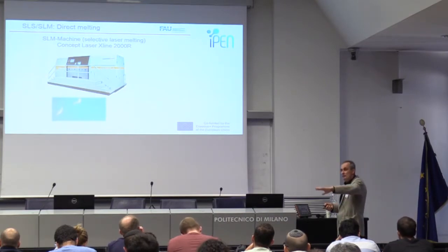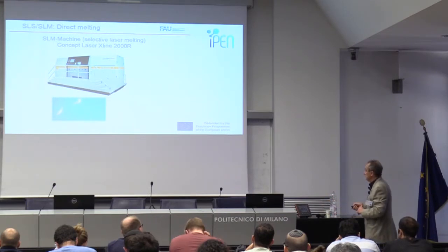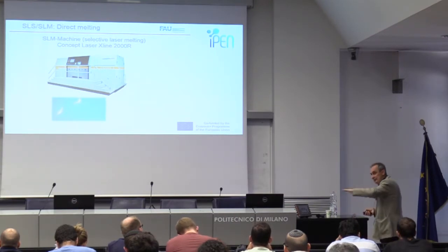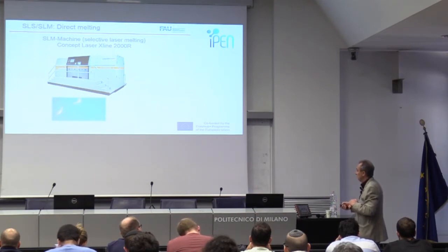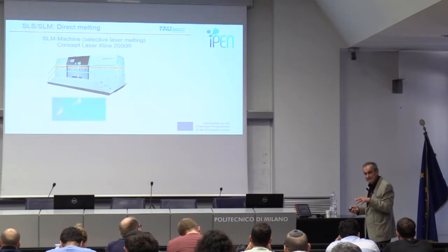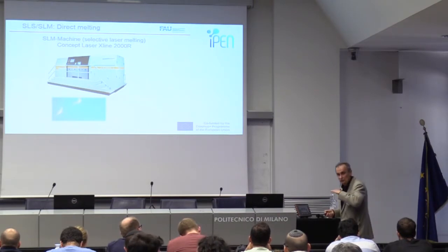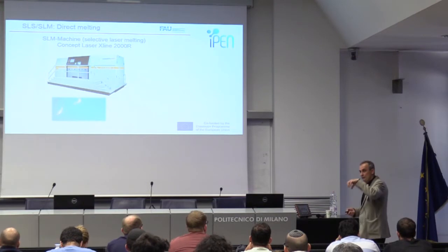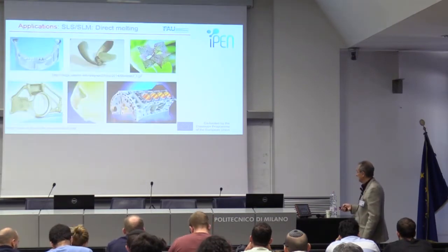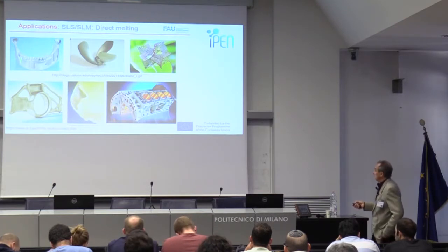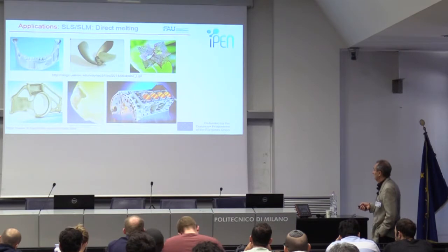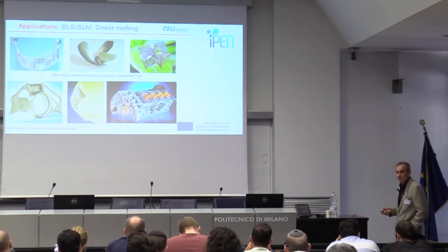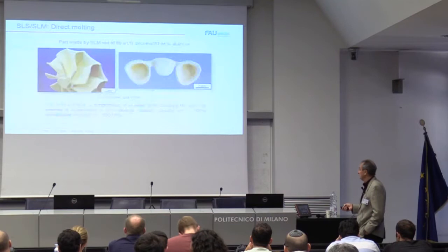You make a sheet of the materials which you would like to synthesize. You sinter with a laser only a small sheet, your slice. After that, you make this casting again, next sheet, next film, and after that you make sintering of the same places. After that, you make again with the doctor blade and again sintering. And in this case, with the laser you actually grow in 3D direction, and the product, of course, for medicine, for dental, and so on, also for engine. It's really possible to melt, because with laser you can melt practically all kinds of materials.